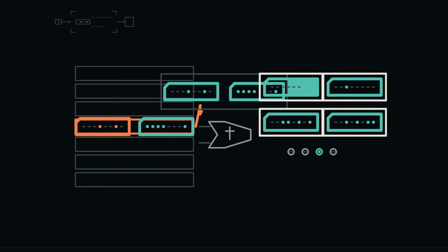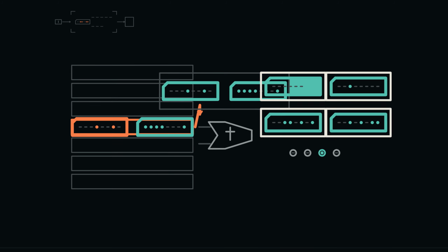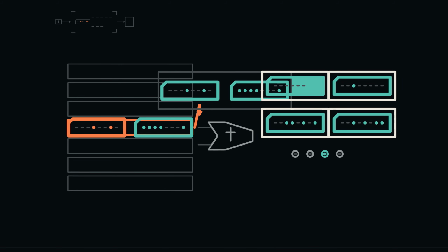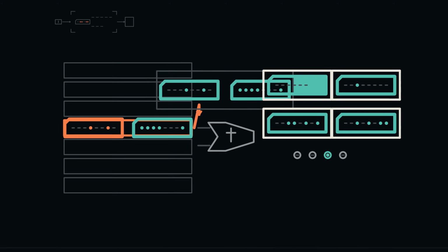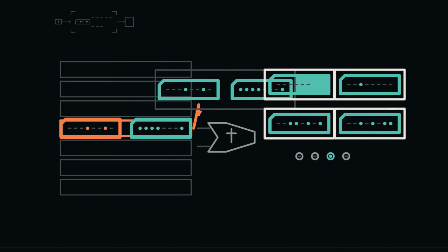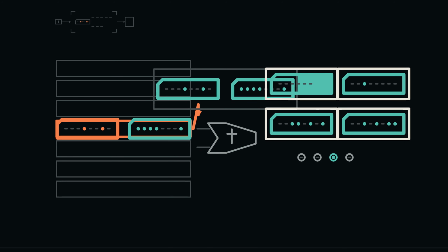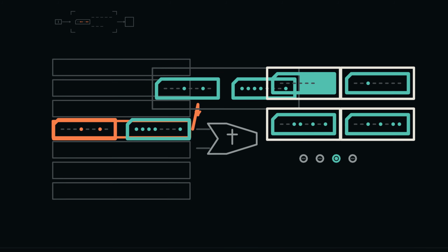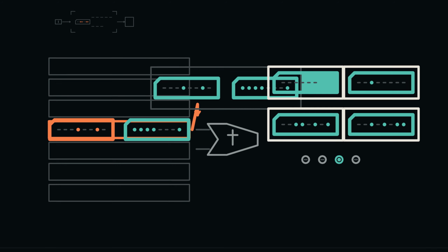A third polling loop now waits for the key press 5. At cycle 175, that separate event places hexadecimal 35 in the queue. A third data load consumes it into R1. The queue becomes empty again. Only now are all 3 requested inputs present in machine state.